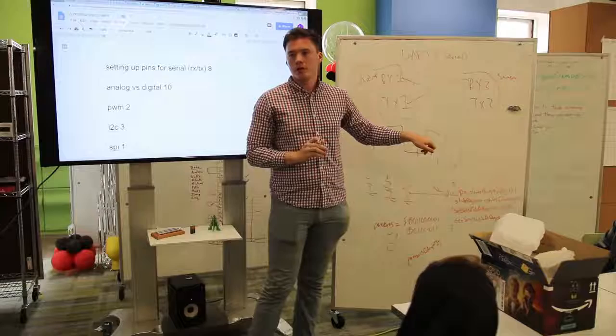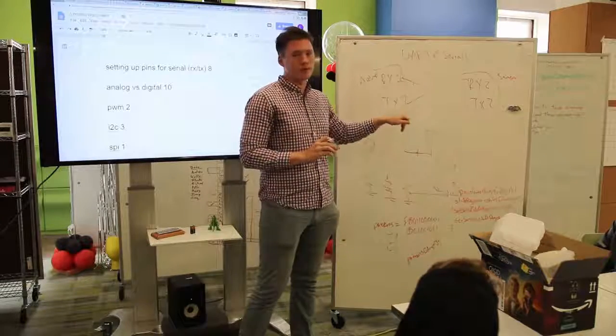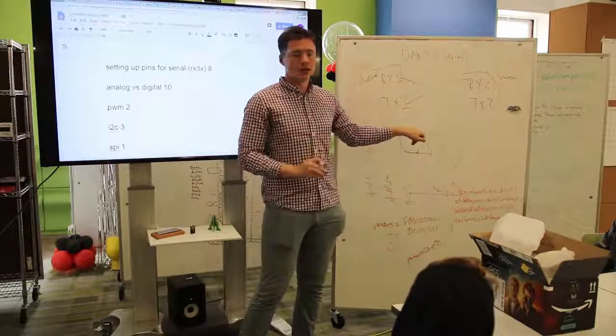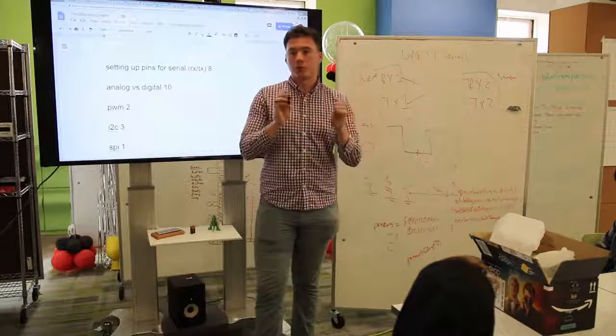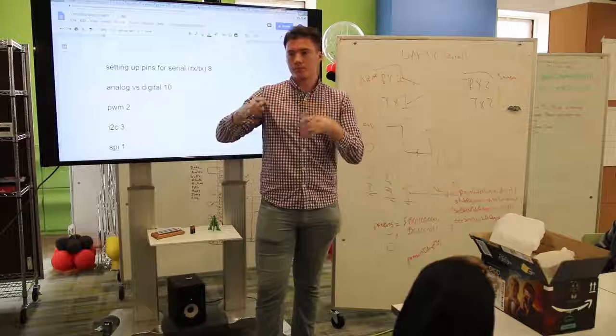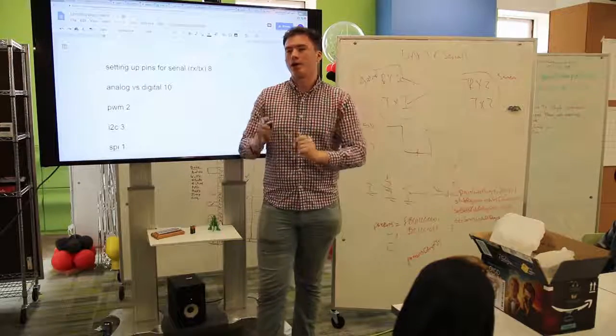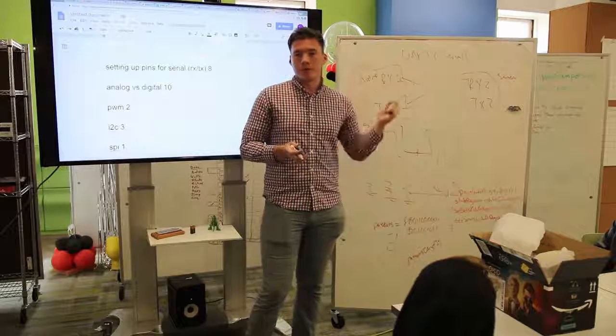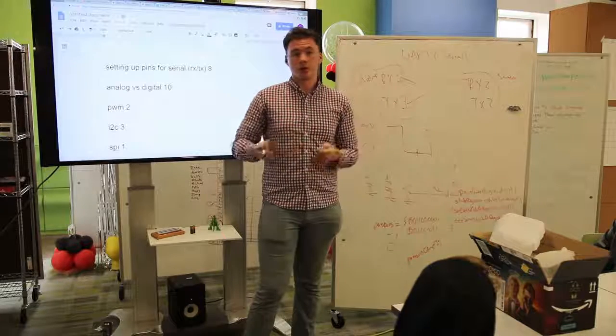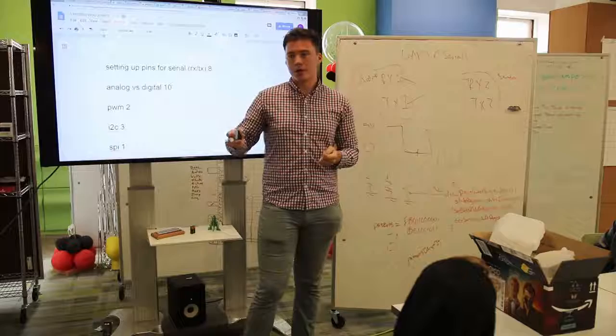Yeah, so you know how I said the baud rate has to do with the hardware in the Arduino? The Arduino has specialized hardware for exactly this kind of communication, built exactly for UART. The problem is, the Uno only has one of those hardware setups. But you needed more, right? Because on the Arduino, pins 0 and 1, if you're not using them for a sensor, you can use to talk to your computer over USB.